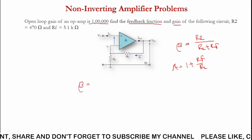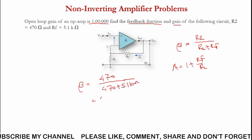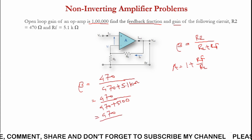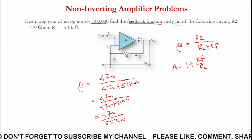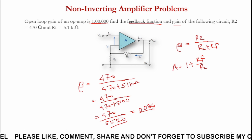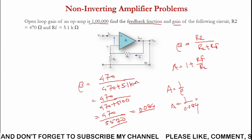So beta is to be calculated as R2, which is 470, divided by 470 ohm plus 5.1 kilo ohms. We have to consider 5.1 kilo ohms as 5100 ohms. So 470 divided by 470 plus 5100, and adding them together, 470 divided by 5570. You can find out from the calculator, it is 0.084. So this is beta. Then A is equal to 1 upon beta, so 1 upon 0.084 is approximately equal to 11.